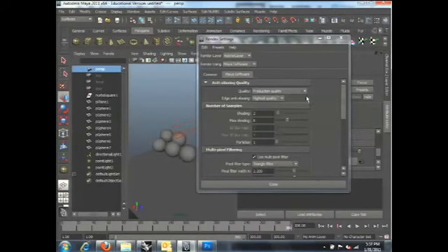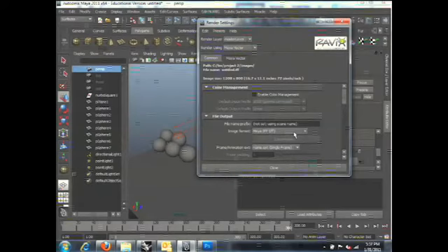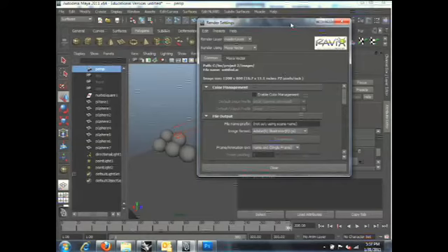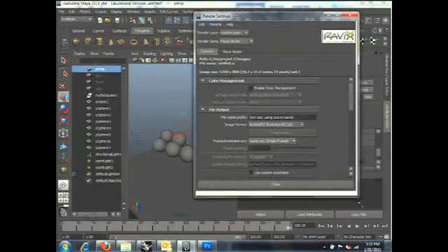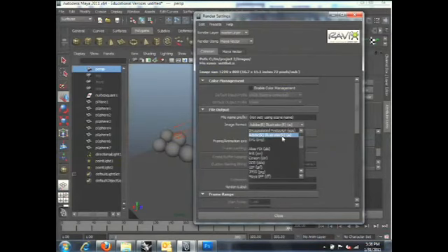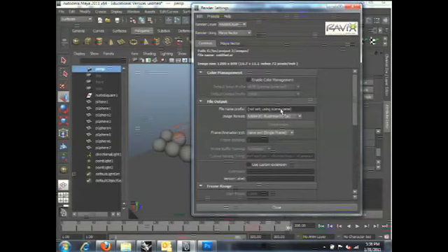So what does this mean, vector rendering? Well, if you switch to Maya vector rendering, you can basically save the file as an Illustrator AI file. So that is a wireframe, a vector format. Does everybody understand the difference between vector and pixel or bitmap? Okay, vector format is like AutoCAD or Illustrator, based on equations, mathematics. The pixel image is based on individual pixels, so they are quite different in terms of the algorithm.